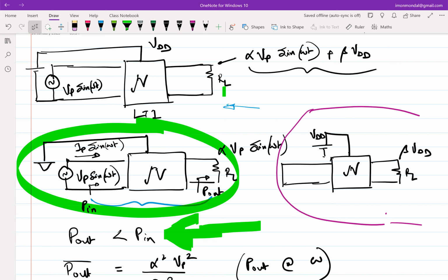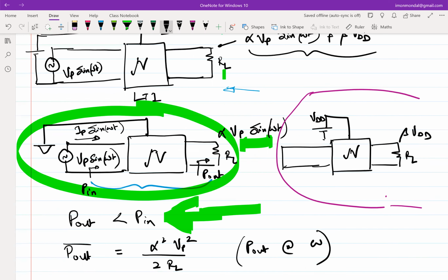So that practice condition, right? It's obtained by individually seeing the circuit and the inequality that will be obtained by the circuit as a whole. They both, right. You are right, but there comes the trick. The trick is that when you put them together, the ratio with which the term on omega and the term with zero frequency get scaled will not change because of superposition, because of linearity. Right? So that's what we'll see when we do the combination.